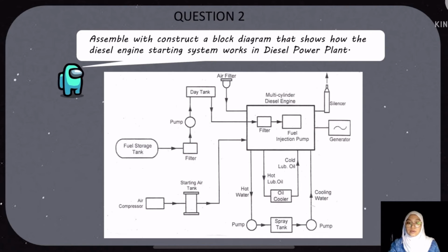Fuel oil from the tank is passed through the filter where the oil gets filtered and the clean oil is injected into the diesel engine through the fuel pump and fuel injector. The mixture of the compressed air and spray of the fuel oil are ignited in the engine and the combustion takes place. The released heat energy is utilized for driving the generator, which produces power.